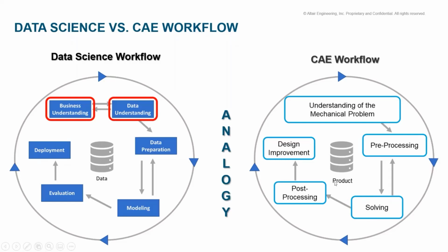Then once the solve is done, you take the results, then you post process it to understand where the maximum stress is, where the maximum strain is, where the stress concentration is happening, and why it is happening. For all these things, you do post processing. If it is a transient problem, meaning the problem is solved in the time domain, then you plot it and understand how the data is varying.